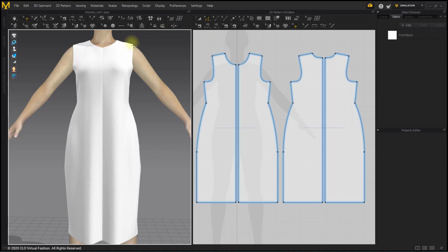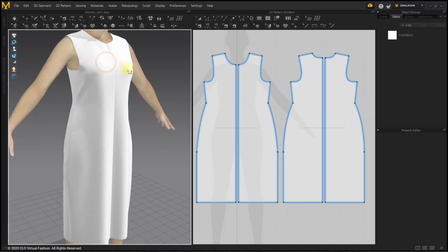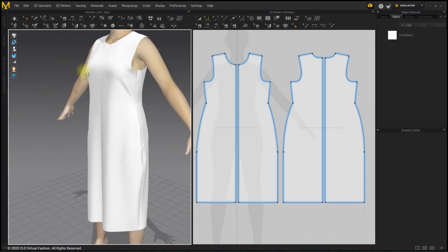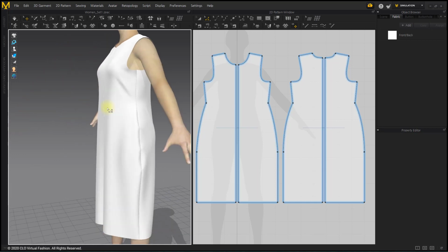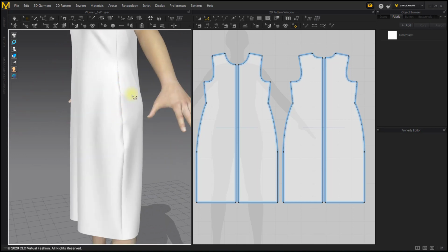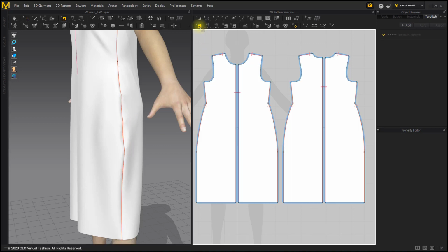If you look at the garment seam line, you'll see that it's recessed. That's because of the angle of the seam. I'll adjust the sewing angle to make it flat. After selecting the side seam, in the Properties window, the fold angle of the seam is set to 220. When it is flat, it is 180, so 220 is slightly inward. The reason for doing this is to make the sewn parts look prominent when exporting to 3D objects.